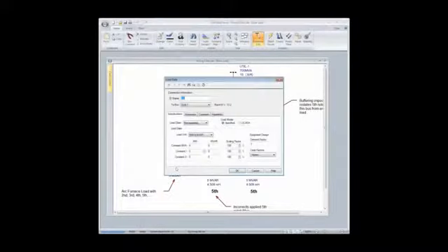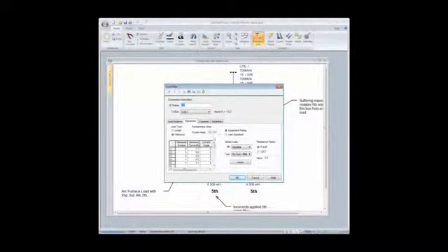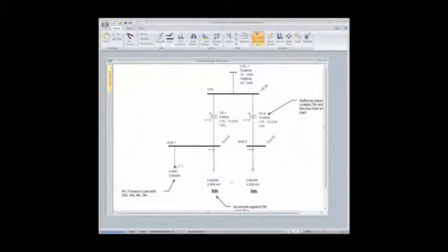If we were to double-click on this load symbol in EasyPower, going to the Harmonics tab, you would see that it's really 2, 3, 4, 5, and 7. That's all there is here. When I was measuring this at an actual installation, these really were the predominant harmonics. Anything above this basically fell off very rapidly. In this condition, given that we have second, third, and fourth, we'll find that applying a fifth harmonic filter may not really be the smartest idea.